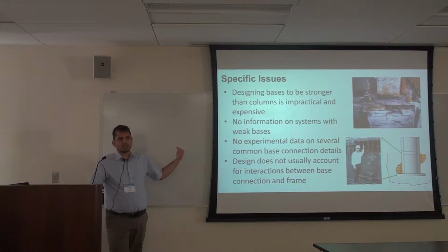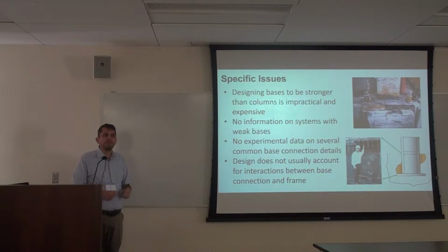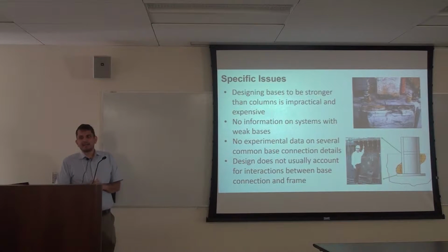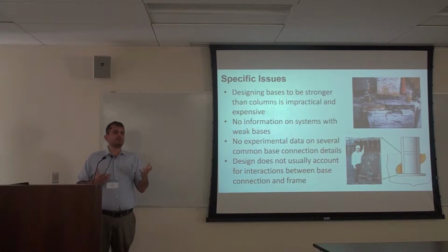Okay, so it's not just that we're designing these base connections to be stronger than the column, we may be protecting, in some cases, the more ductile element from the brittle element by making the ductile element stronger. So there might be things we're getting backwards.